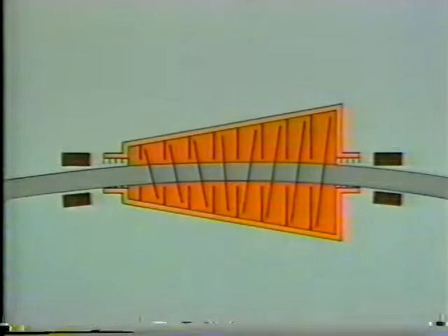When a turbine is shut down, hot vapor rises to the upper part of the turbine casing. This means that the upper half of the turbine is at a higher temperature than the lower half. If the rotor is kept stationary, the cooler lower half of the rotor would contract quicker than the hotter upper half. This uneven contraction causes the rotor to bend or bow.